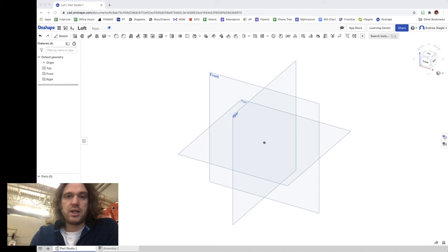Now take a look at this chess piece that a student made. If you're looking at this, you can see that it wasn't extruded. It looks like it was almost an extrusion that's been pinched. What the student did is they used the Loft tool. They had maybe a loft for this main column of the shape, a loft probably for one of these spires, and then they did a revolve for the eyepiece. So pretty simple way to create the ever-seeing eye of Sauron.